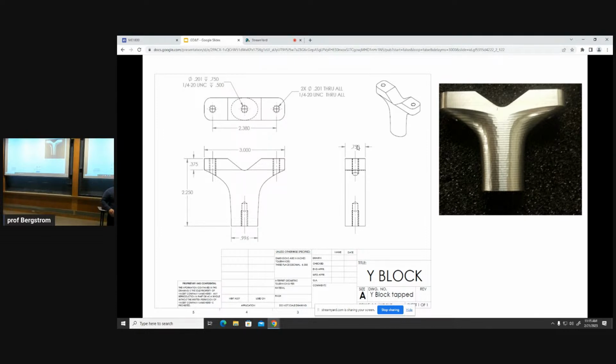Why did I pick plus or minus 5? There are different types of fit, like clearance fits. Well, all right, so I set it here for my tapped holes. So I said what hole diameter to drill, and then what thread to put in it. And here I'm willing to accept plus or minus 5 on the diameter of the hole. I'm willing to accept plus or minus 5 on the location of the holes in space, all the dimensions, right? Why did I pick plus or minus 5?